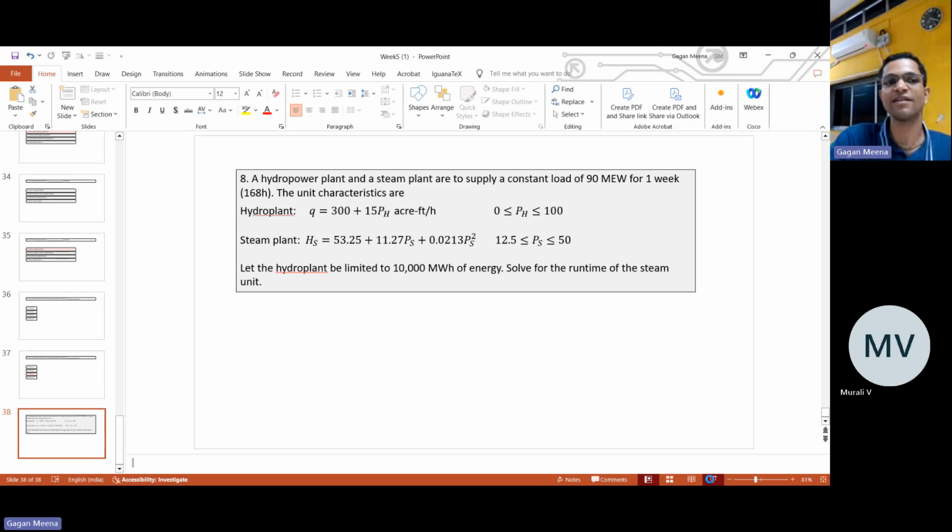In a few months of a year, Karnataka experiences excess generation. So they are managing the variability of renewables using hydro. When the renewable generation suddenly reduces in the next hour, they use hydro.